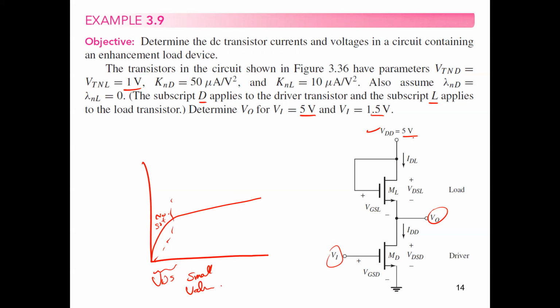So once we apply 5 volt in input here, this is going to be active high signal. In this case, since this is an inverter circuit, the output volt would be low. If you consider it's working in saturation, it would be wrong, so you have to repeat the problem again. It's now a kind of taking more time to get the solution. However, if you know the circuit by experience, from the beginning you can assume the right solution.